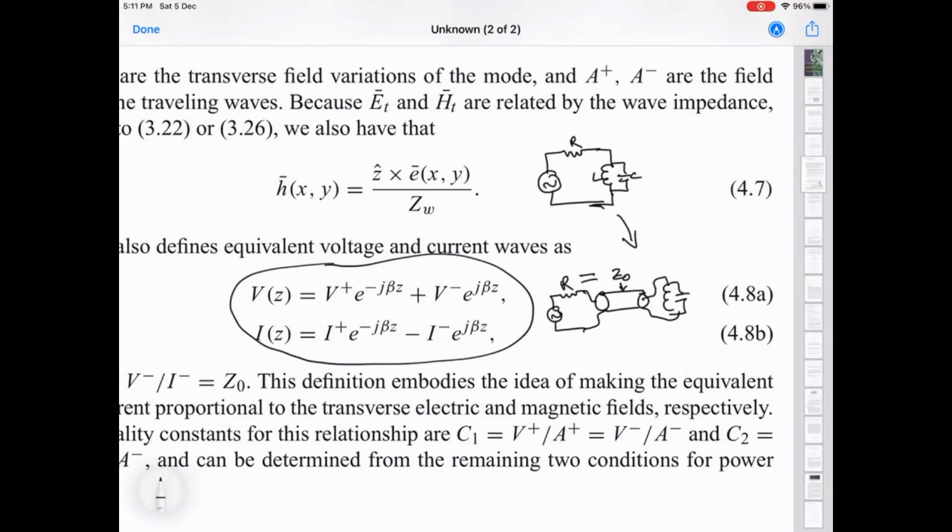Now, we sort of know from our previous discussions that if I just consider this part, everything outside of the LC resonator, this is just a transmission line of Z naught connected to a voltage source of the same impedance. So what happens is, in some sense, nothing. There's nothing complicated happening in terms of reflections, because this is matched here. Any wave launching from the source will not experience any reflection here, and it will propagate up to this end, and then here it interacts,